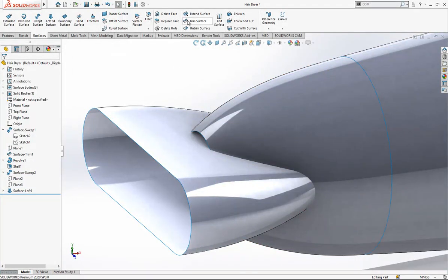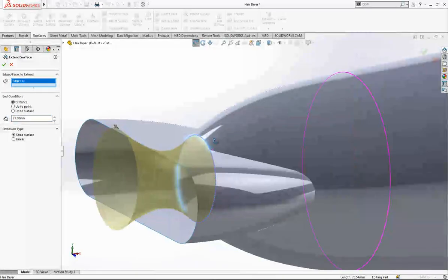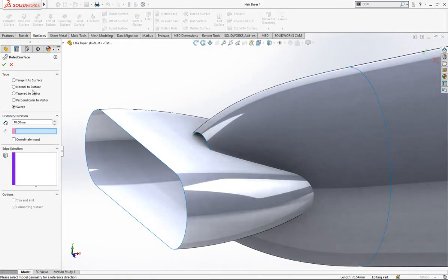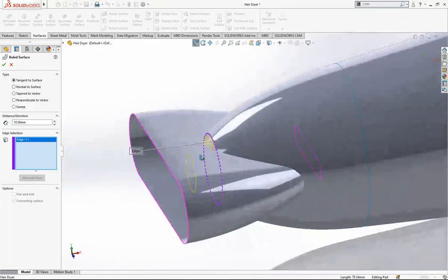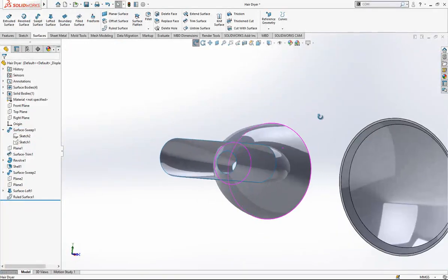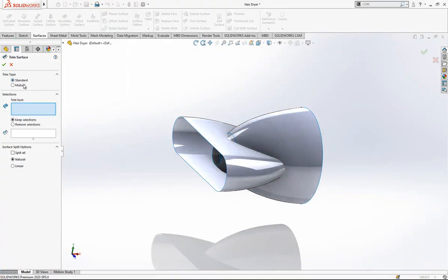Okay. Then we make an extend surface. Oh, this is becoming like a parabola. Revolve surface here, good. Tangent to surface. Edge selection. We can extend some amount. Yes, we then have 3 surfaces, body and extended, and then this loft operation, and we're going to make a trim.